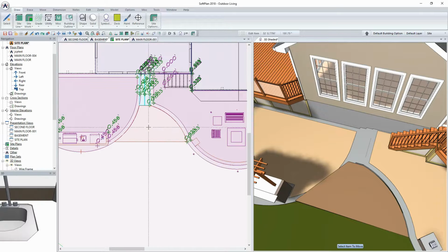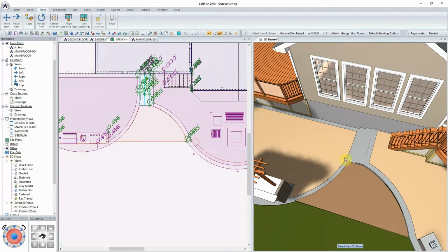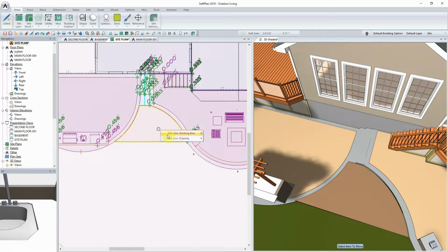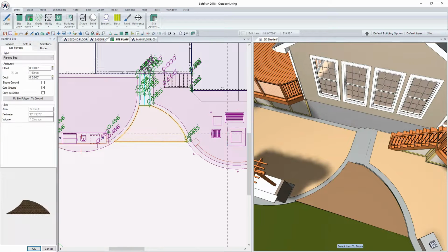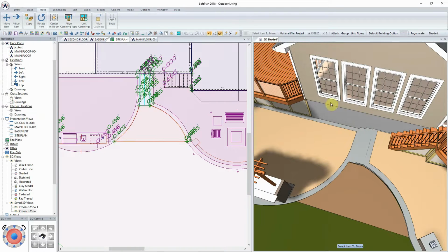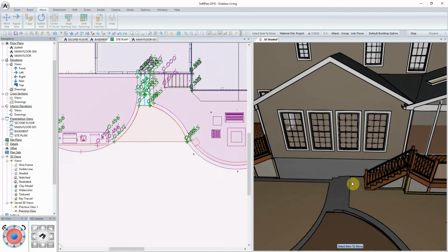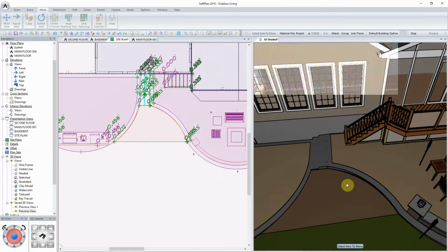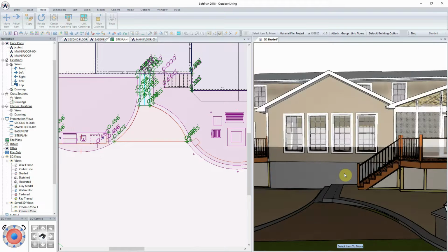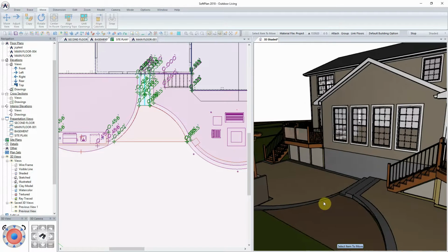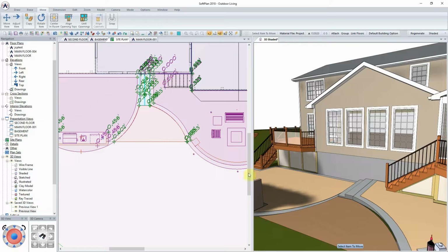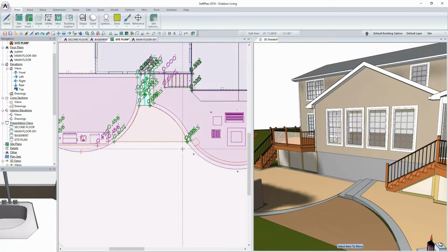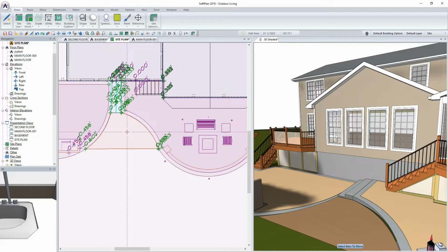And as I zoom this out in plan, and as I also view this inside 3D, I can see what this is doing. I can edit this after I have modified the radius and so on, and I'm just going to fit this site to the ground, which is going to allow it to actually follow the curvatures of the ground itself. And so we now have that planting bed in place. Okay. And so as we move forward with this, we'll be able to go in and modify both elevations on that according to what the shot points are, as well as different thicknesses and so on of the individual poly.